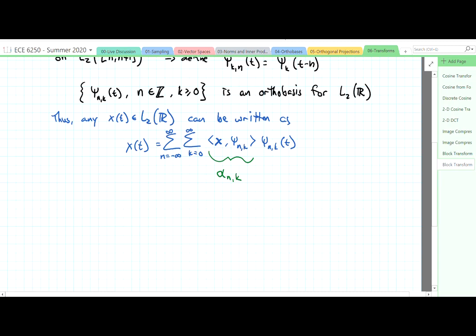It's two dimensions. You have your time offset, your block offset, which corresponds to n in this particular case, and then you have your frequency, which corresponds to k. Now there are a few subtle differences. One of those is that with the spectrogram, we often have the blocks overlapping, but here the blocks aren't overlapping. Is I guess the main difference.